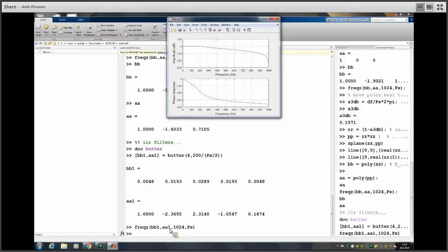So we basically improve the previous Chebyshev by moving those zeros from that one single location and distributing them. 6th order. So by choosing the correct kind of IIR design, you can cut the amount of calculations down by a factor of 2 at least.